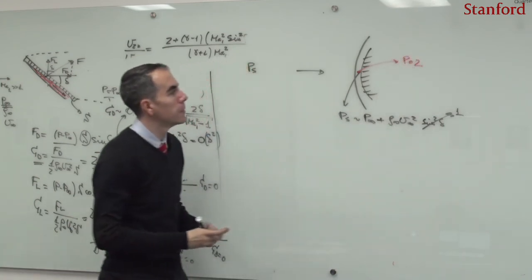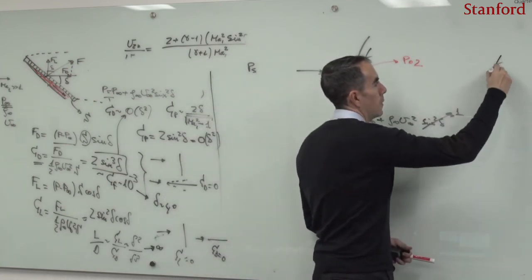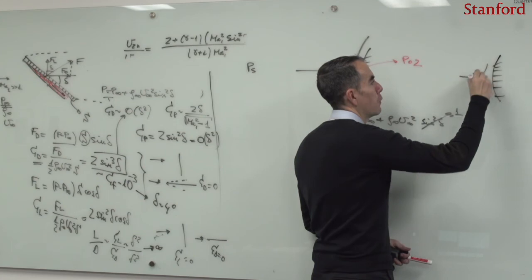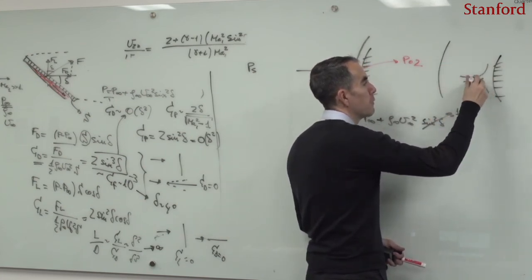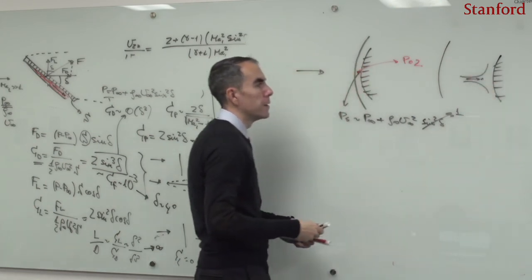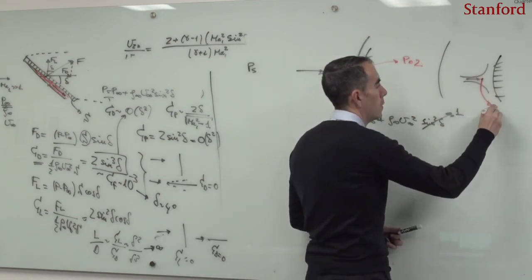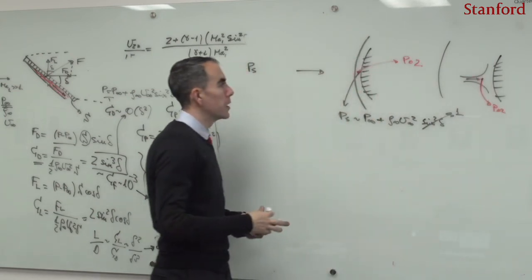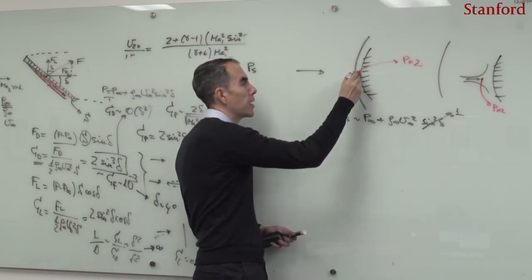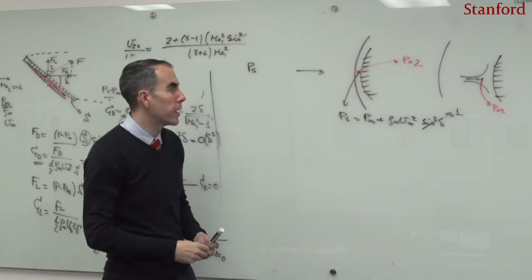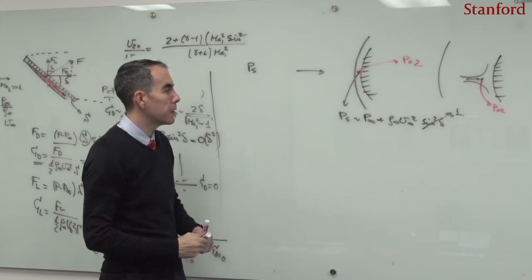stagnation pressure. So remember that if I zoom here, close to the surface, what one sees is a sort of stagnation point flow. It will be the shock wave. Stagnation point flow in which the flow recovers the stagnation pressure. As you can imagine, the wave drag on this blunt body is going to depend very much on whether one captures this stagnation pressure correctly or not, right? And it appears that the Newtonian theory wasn't predicting it correctly.